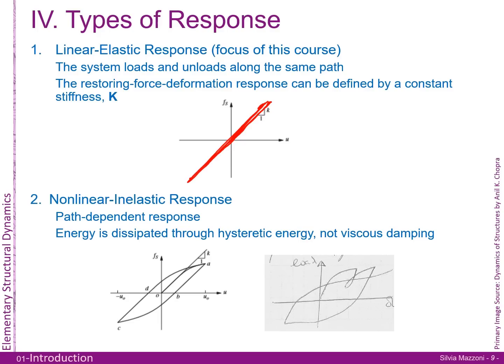Then you go to nonlinear inelastic response, and now it's not really time dependent, it's a path dependent response. Energy is dissipated through hysteretic energy, not just through your viscous damping that you do elsewhere, but even just these cycles where it doesn't quite reload along the same path. Here's a nice sketch that I had drawn. Anything that is this area under the curve that isn't recovered, it means it's energy dissipation. And guess what? That's a really good thing. You want energy dissipation, whether it's through inelastic response, but you want controlled inelastic response versus uncontrolled in brittle systems.